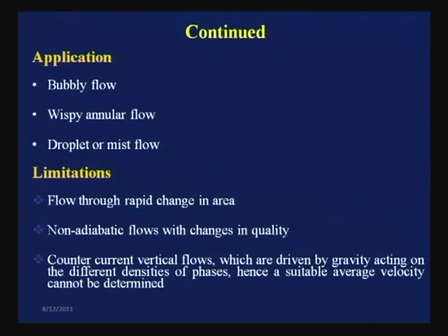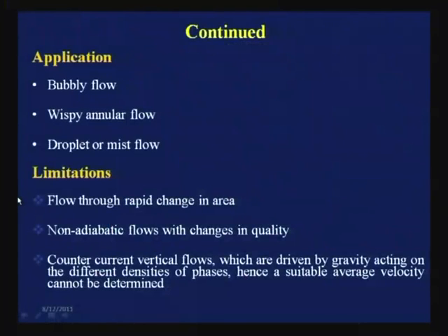Under this rapid acceleration, we cannot have the two phase flow situation. This I have already written down here. So, for the rapid acceleration, what is the problem? Let the two phases accelerate. Why can we not use it? Because under such circumstances there is a drastic change in pressure. The moment there is a drastic change in pressure, flashing occurs. The moment flashing occurs, thermodynamic equilibrium is no longer valid. Clear to all of you?